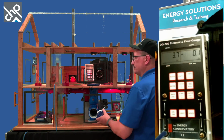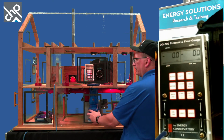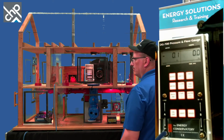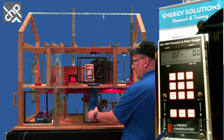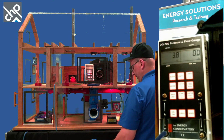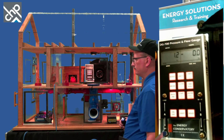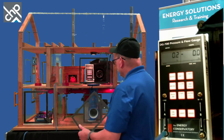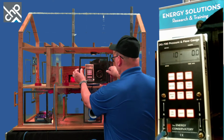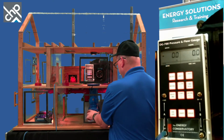So I'm going to close this back up. The pressure you'll see will start to go back close to zero again. And same thing as before, if I had a really leaky house, let's make the leak back. If I got a really leaky house, when I open the window here, that pressure doesn't even show up until you make the house tighter. So I'm going to put this back on, put the leak back in here, and then we're just going to recap real quick.